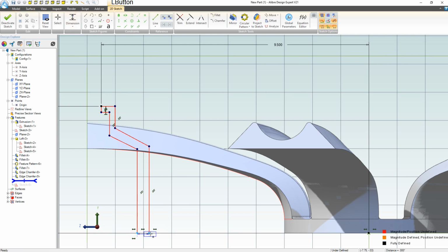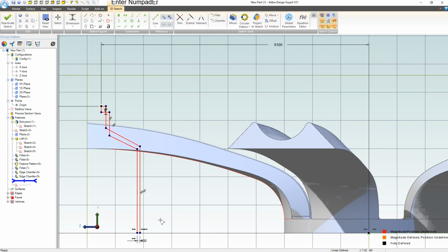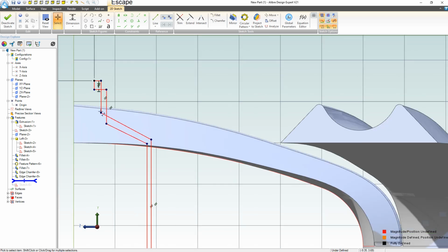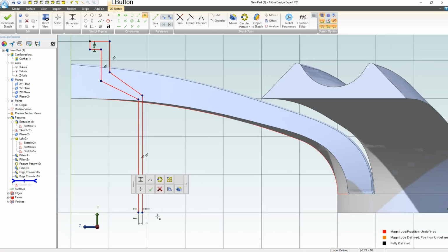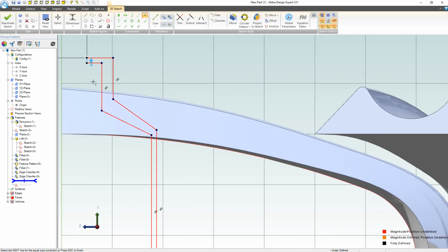And how thick do we want this? I don't even know what the standard thickness is for wheels. I'm going to take a stab or a guess. I'm going to call it 0.1 inches. And of course we have a little bit of overlap here, right? So I'll draw a line from here to here, and that gives me the opportunity to add in a few relations. We're going to grab equal from here to there. That ensures that those are equal. And then for design intent, we can grab in some construction geometry.